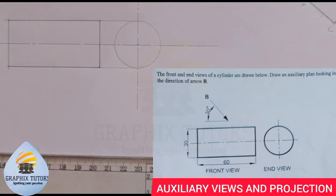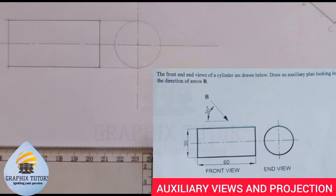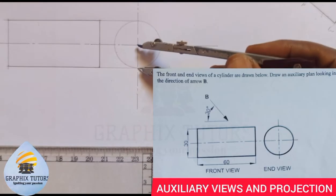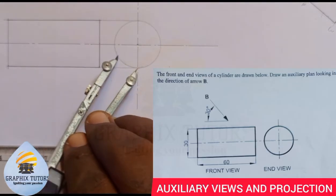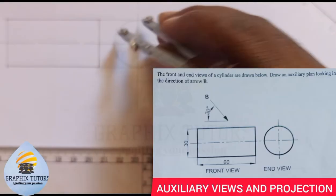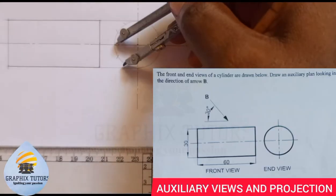So the first thing I will do is to divide here into 12 equal parts. Just take your compass, place it from this end to this end, and you mark up. Come to this end also, you mark up. Then you come here, you mark up and down.